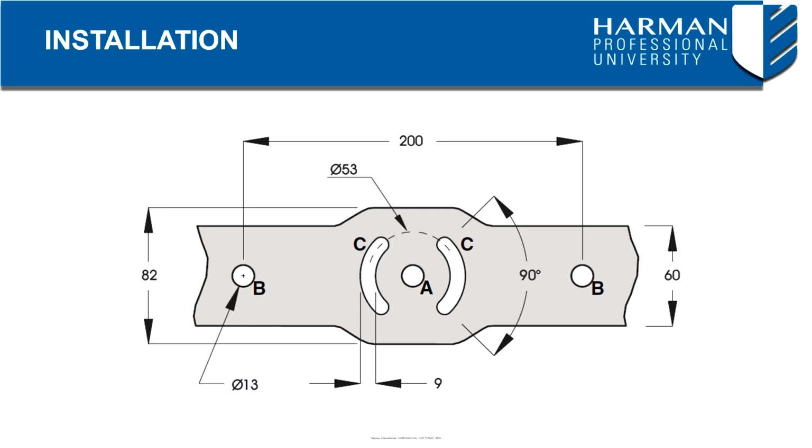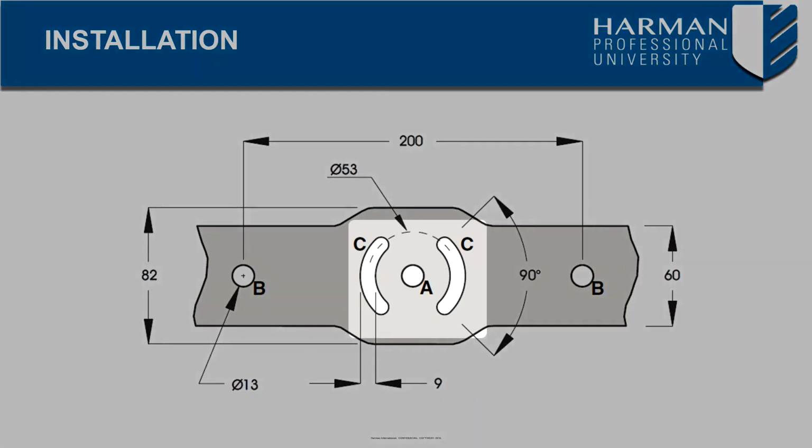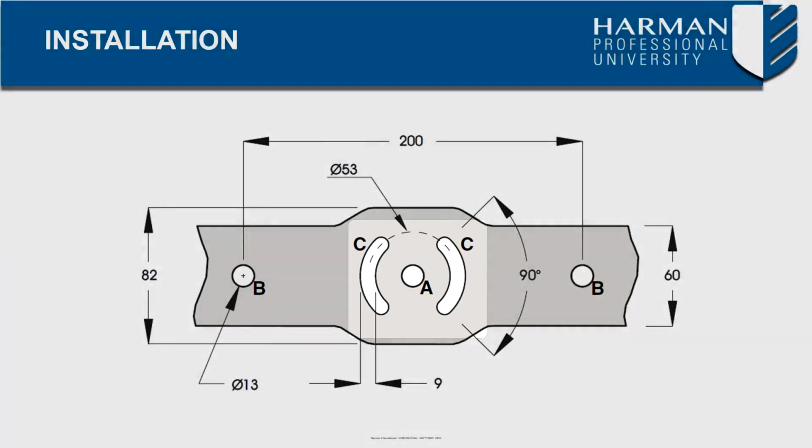To mount the fixture's mounting yoke base to a flat surface on a wall, pedestal, structural beam, or other suitable support, the yoke base must be securely anchored. The yoke allows the fixture to be manually panned and tilted for beam aiming adjustment. Fasten a 12mm or 1/2-inch diameter bolt to the surface through the center hole A in the mounting yoke. Fasten 2 bolts with 8mm or 5/16-inch diameter to the surface, with 1 bolt passing through each of the curved slots C to anchor the fixture.